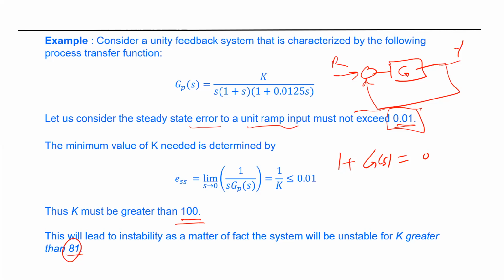For example, suppose you add 100 and you check the stability by Routh-Hurwitz, and it becomes unstable, so you have to reduce. Honestly speaking, this method is not that powerful. It's just an indicator, okay? If you want real design, you go to the phase margin and gain margin.